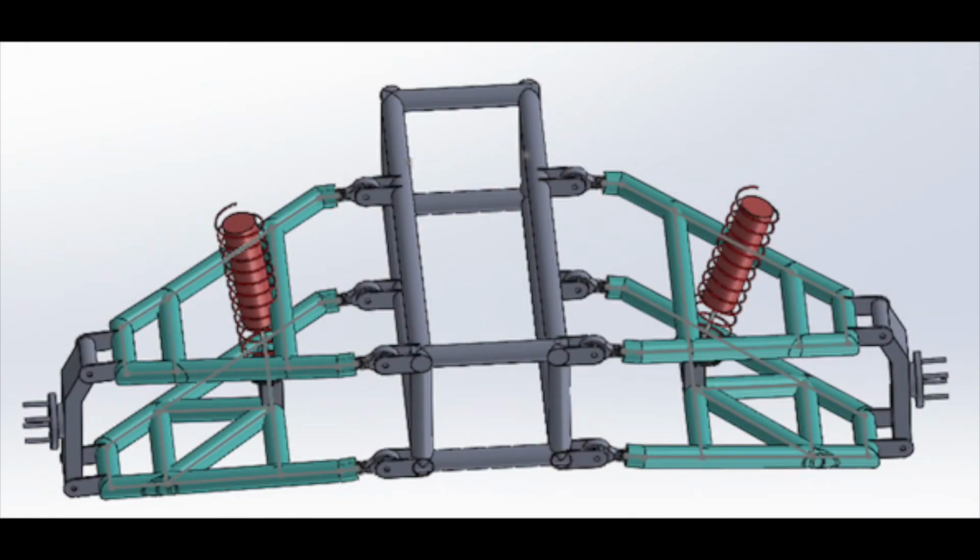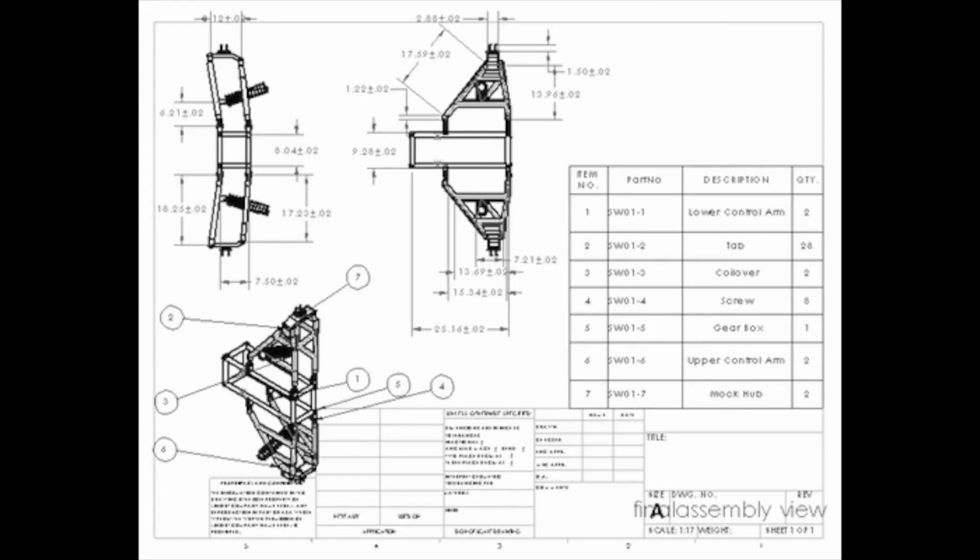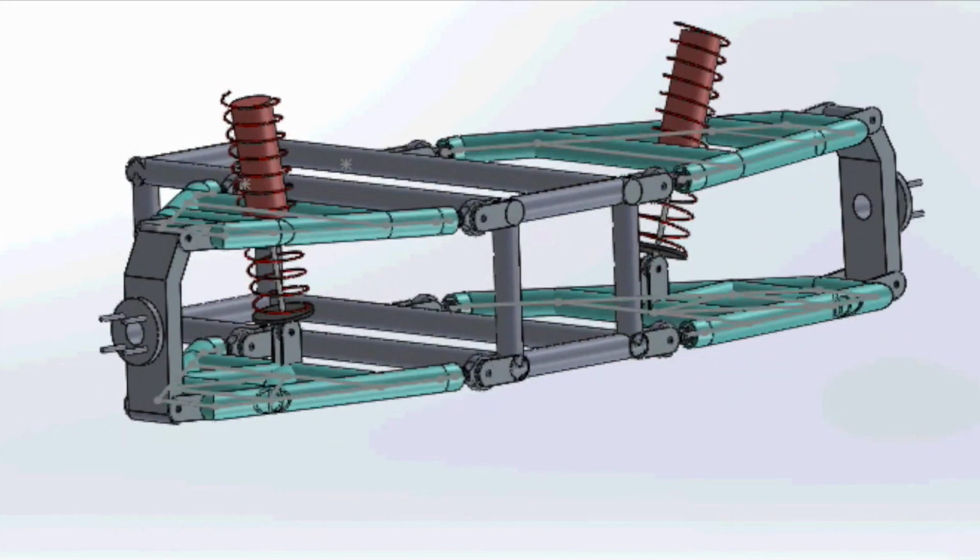This is the new suspension system that we made. The blue components are the new control arms we redesigned. As you can see, the upper arm is shorter than the lower arm to give the wheels more negative camber, about 15 degrees in difference. The red coils were also redesigned to be longer, with a large bushing mounted between the chassis to provide more support and additional shock absorption.